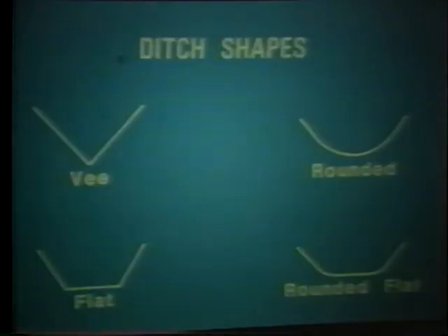And the shape of the ditch influences both vertical and horizontal actions. The right combinations of front and back slopes and ditch geometry need to be selected to reduce both actions. Safety can be improved simply by regrading the ditch profile to a slightly different cross-section. Evaluation was made of computer simulation and vehicle tests on slide slopes of 4 basic ditch shapes.